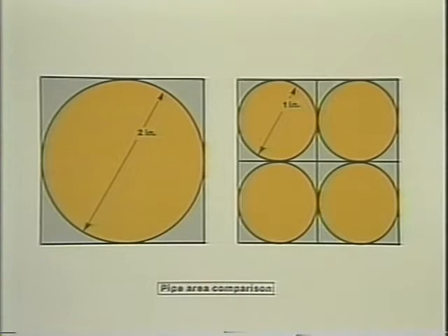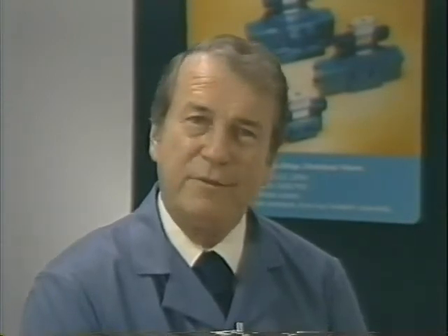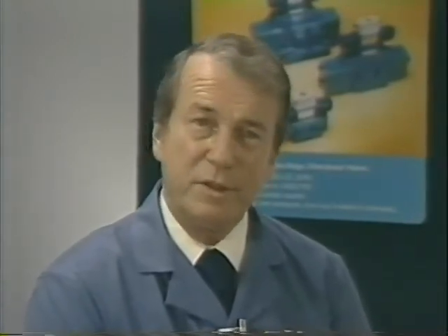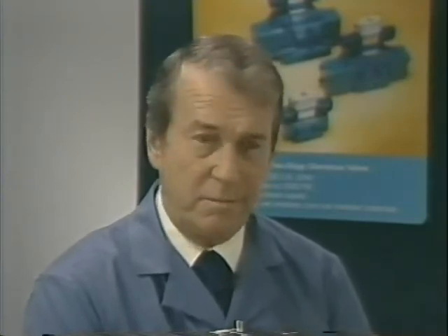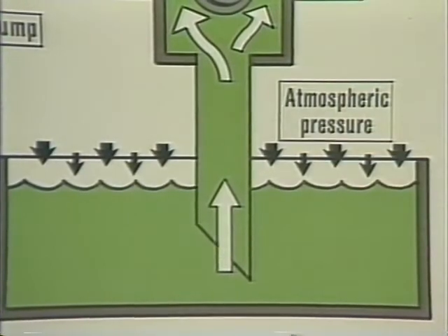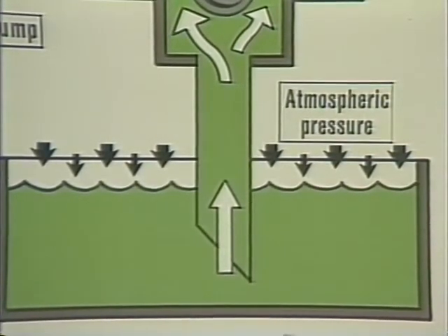That means the same amount of fluid would have to move 4 times as fast through it, and the friction would increase proportionately. Now, what does this mean in practical application? If you must replace a line, use the same size or a little larger, and avoid as many elbows and bends as possible.